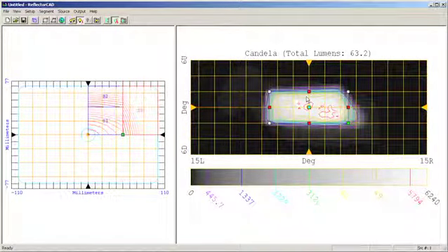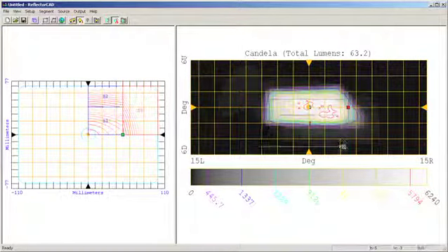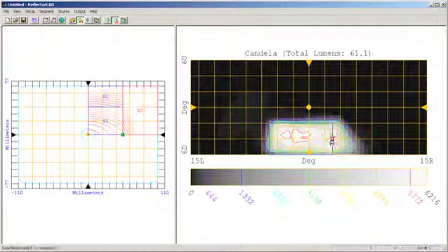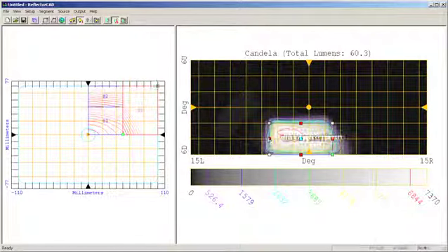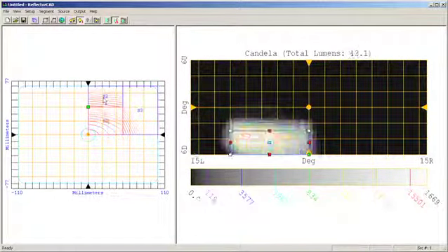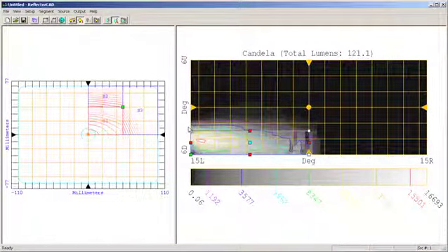This is a luminous intensity pattern from the third segment. I'm ready to reposition this third segment to give the desired performance that I want from this segment. You will note in the design that I'm doing, I'm actually tilting or adjusting the luminous intensity patterns from the inner segments to correspond to the luminous intensity pattern on the outer portion of the beam.